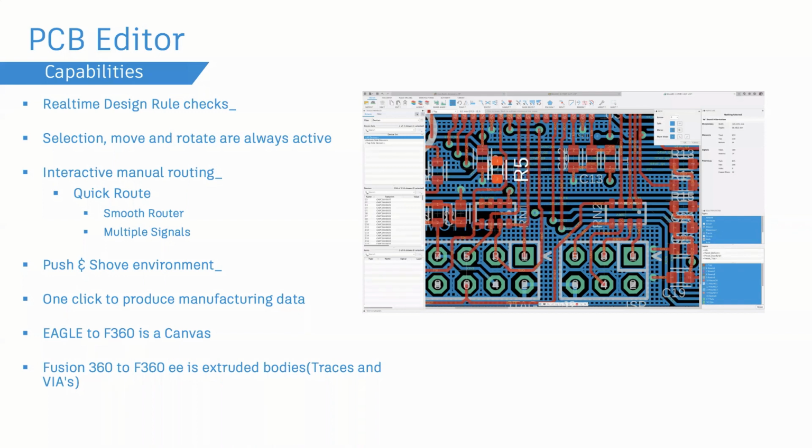Now, creating your Gerber files, we have a couple of options, and we will go over that today, which is one click. It will create all your Gerber files zipped up, ready to go. Or if you need to make some manual changes to your output, because you used additional layers and put some artwork in additional layers, you could always execute the CAM processor. That way you could use those layers as well.